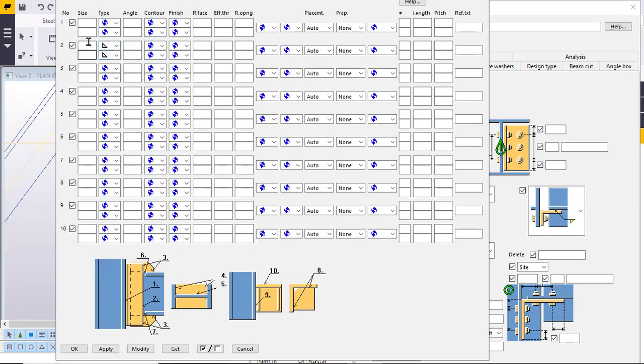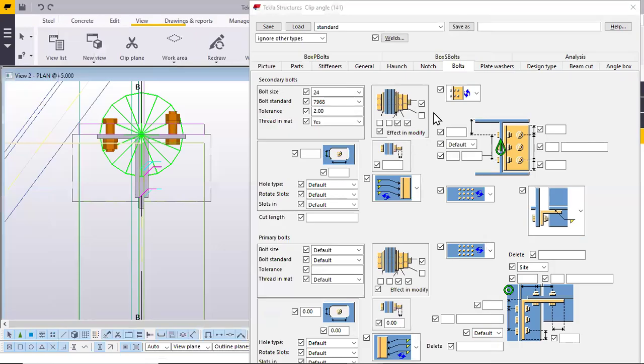So whichever number is there, only in that number you have to add the weld. You should not add the weld anywhere else. And other things you have to keep blank like this. I'll show you. Okay. Modify. Okay, so this is how weld should be applied.